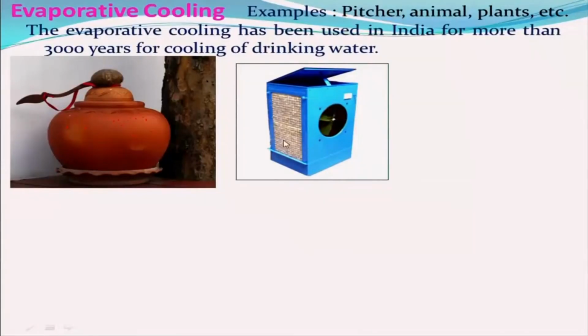And we use this thing also in our coolers, which we call air cooler, and this is known as desert cooler also, or swamp cooler. What happens is, if it is dry, that means not much water vapor is there in your air, like in the northern belt of the land, like Kanpur, New Delhi, Rajasthan, other places before the monsoon sets in. This is a very beautiful system, which of course I use in my home, this cooler.